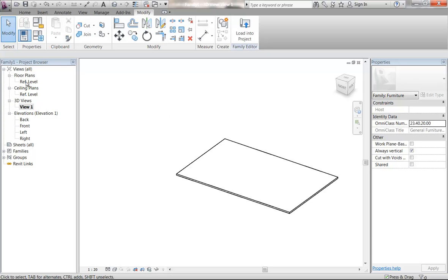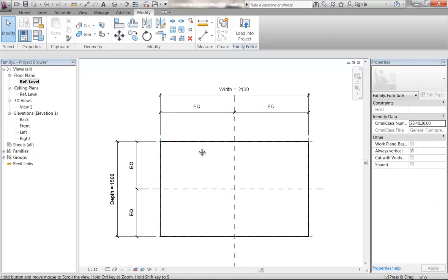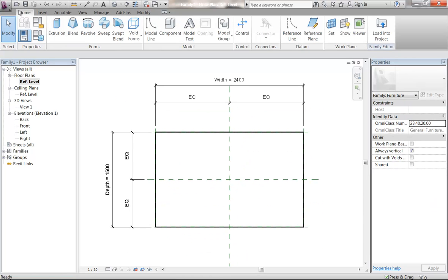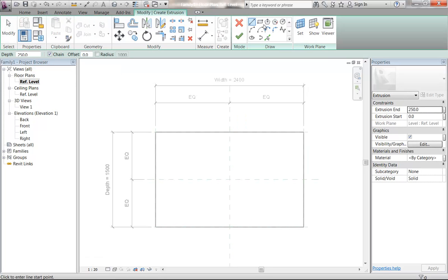So I'm going to go back into plan and make some more extrusions. So again, just with the rectangle tool, I'm going to click onto the corner there, and then up to the top edge. I'm not worrying about the width. I'll come back and do that, but here it's really important that I do snap to that top edge, just somewhere. So that way, you can see I've got the 3 padlocks, so I can lock the 3 sides that are on the edge of the desk already, but this one last side that isn't, I need to do a different way.